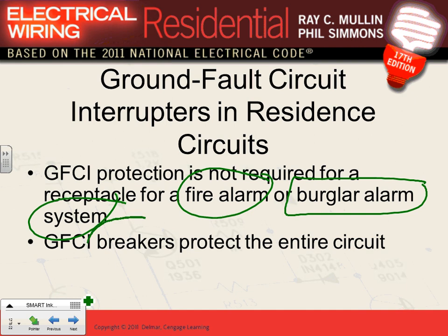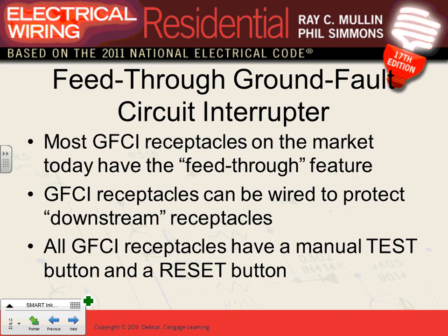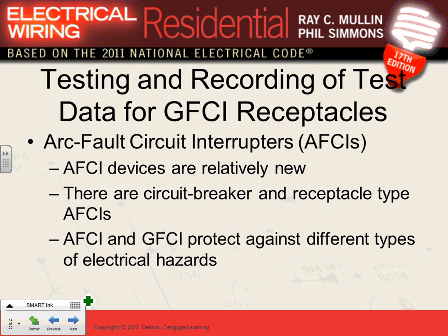With GFCI, you can have them as breakers. Typically, we don't use a whole lot of GFCI breakers, but you can have a GFCI breaker that protects the whole area, or you can have receptacles. What we typically use is receptacles. Okay, got that one. A lot of GFCI receptacles are feed through, and we have a couple of pictures we'll show you. You bring the line in and the load out, and you protect it. And a GFCI has to be tested. So there's test and reset monthly. You're supposed to push the test button, reset, and make sure it works. Any comment about GFCI before I move into the AFCI? So that's basically what the GFCI notes are. A lot of it is review for you.